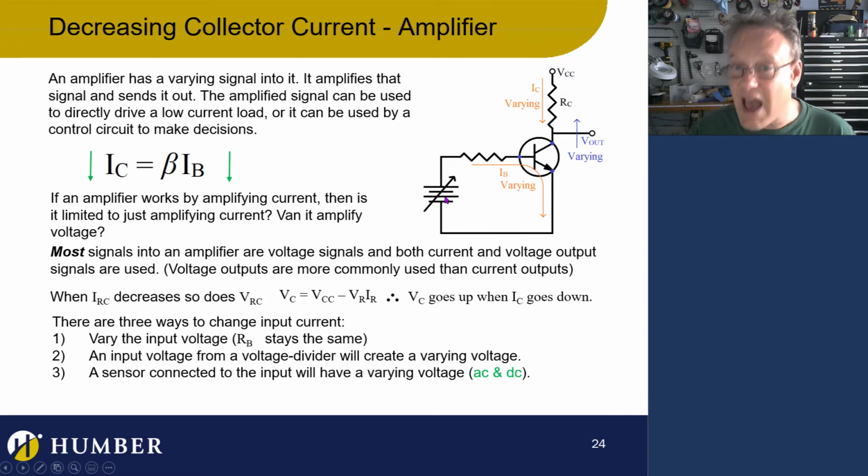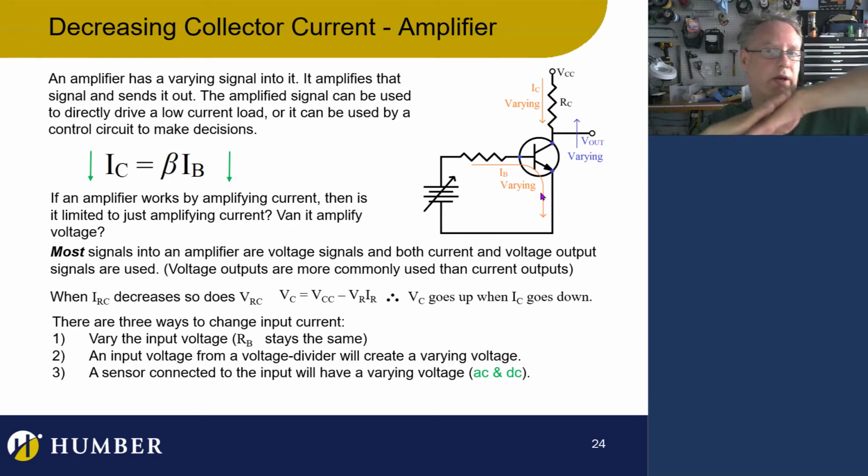If this is 5 volts, let's just say I needed exactly 5 volts here, and I chose a specific resistor there so that when I put 5 volts here, the current going through here was fully saturated, right? So it's a fully closed switch. Exactly when, if I put 4.9, that switch wouldn't be closed all the way. That BJT would be almost closed. There's just a little bit of a gap there, right? But if I put 5, boom, it's closed.